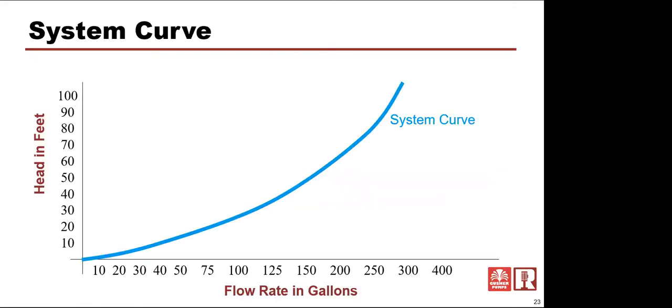So this is one system curve. Okay, so we know that as flow goes up, there's more resistance to this curve. I can tell you by looking at this curve right now that there's no effective lift in this curve. If we were lifting, like say 10 feet in the air, this pump over here at zero flow would be up at 10 feet because it would take that just to start getting some flow. So that curve would be a little different if say we were lifting 10 feet or 20 feet, it might start off here and come up.